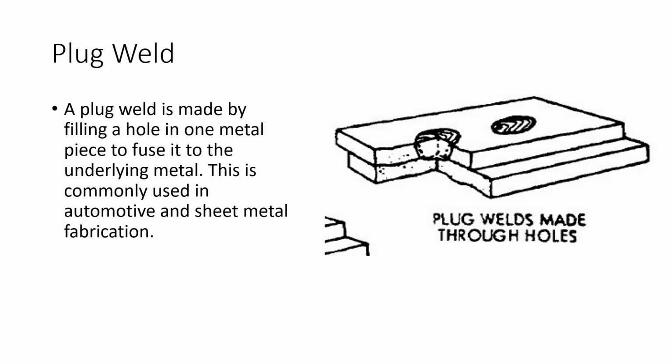This is a plug weld. This would be where we'd want to weld two pieces together, one on top of the other. So then we'd cut a hole in the top piece and then puke a bunch of metal down into that hole that we just cut in there. I don't know, puke, but anyways, you get the picture. We would deposit a substantial amount of material into that weld preparation. This is a plug weld. Generally sheet metal and stuff. You're probably not going to see this on 9-inch pieces of plate or 4-inch pieces of plate.